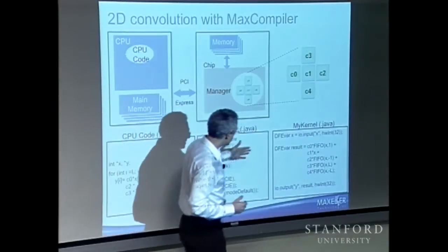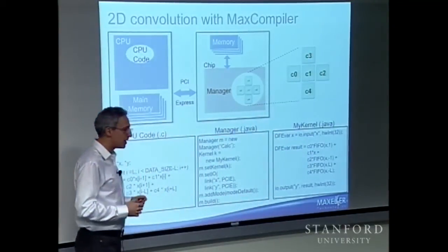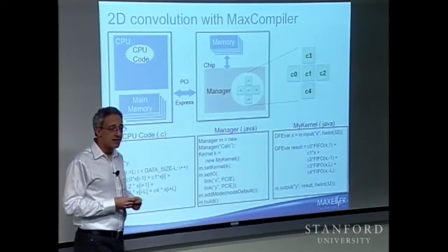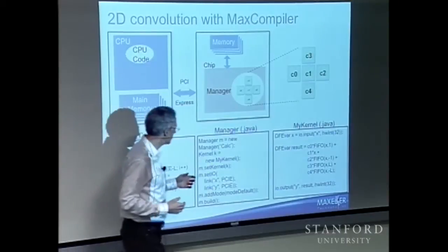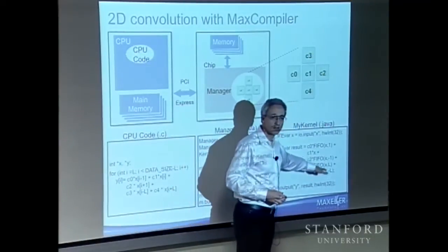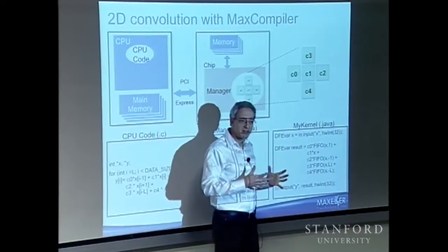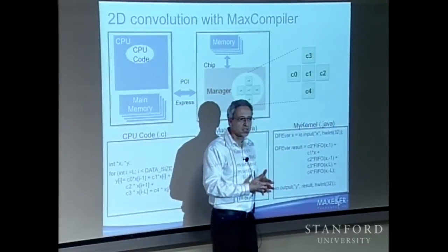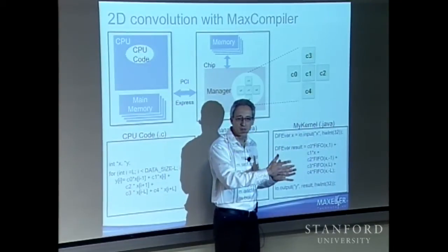The way we are writing this is simply the same way as it would look in a regular program, except that your index into data turns into delay FIFOs on the hardware side. So instead of a register file, you're simply storing the numbers locally inside of these little memories.